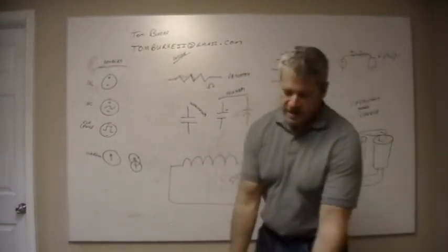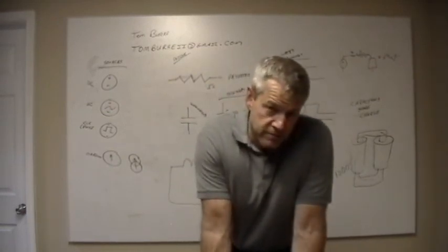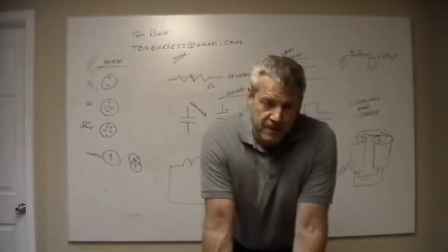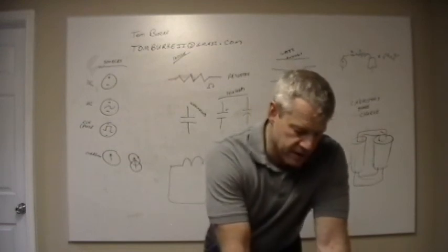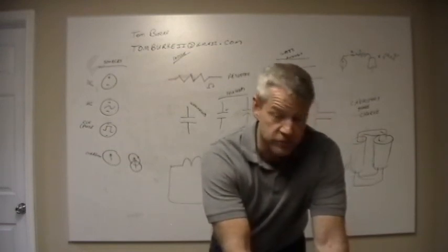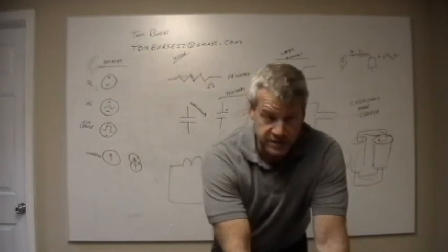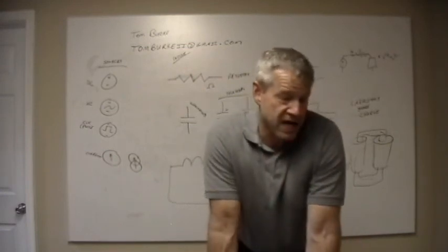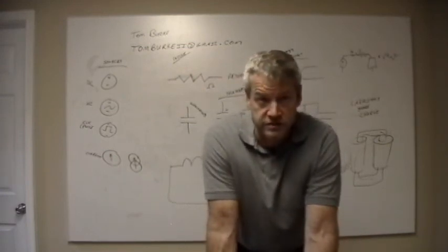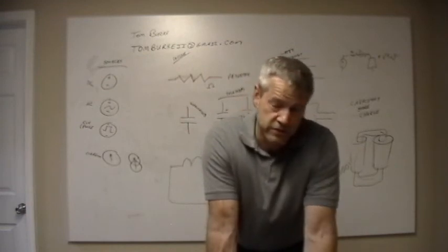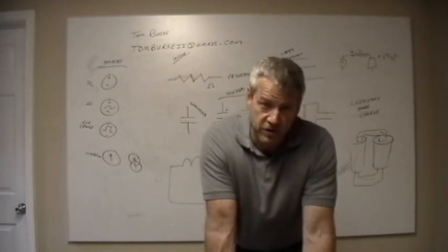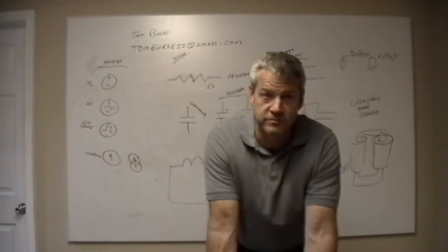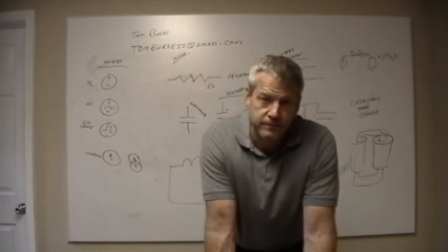And I would suggest for that, you can buy an Arduino for $25. An Arduino Uno, which is a nice simple board that's about that big. It's got an Atmel, which is now Microchip, ATmega328P microcontroller on it. It's got up to, I think, 5 analog channels, some pulse width modulation capabilities, 16 or so digital input outputs. For learning and for simple projects, it's a great tool. I'm actually using one at work right now to do a lot of data logging. A lot of flexibility.